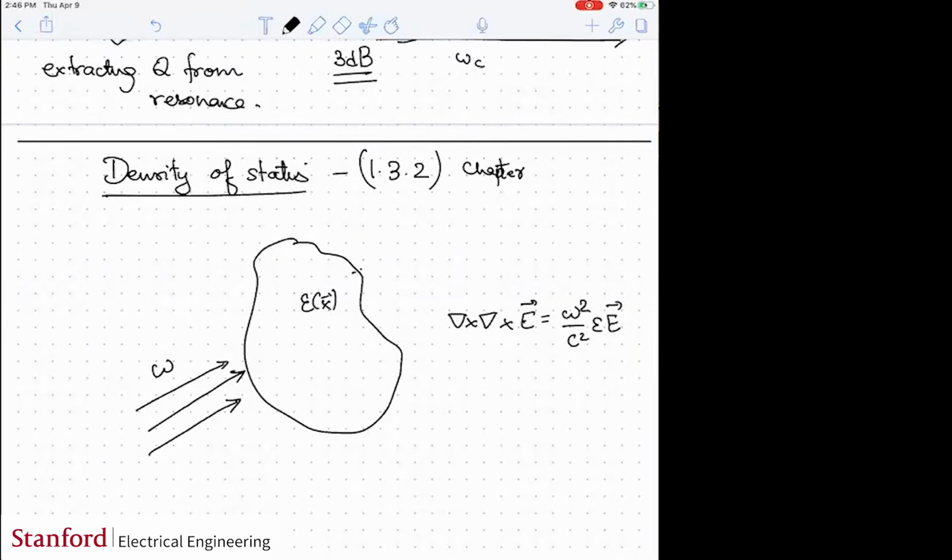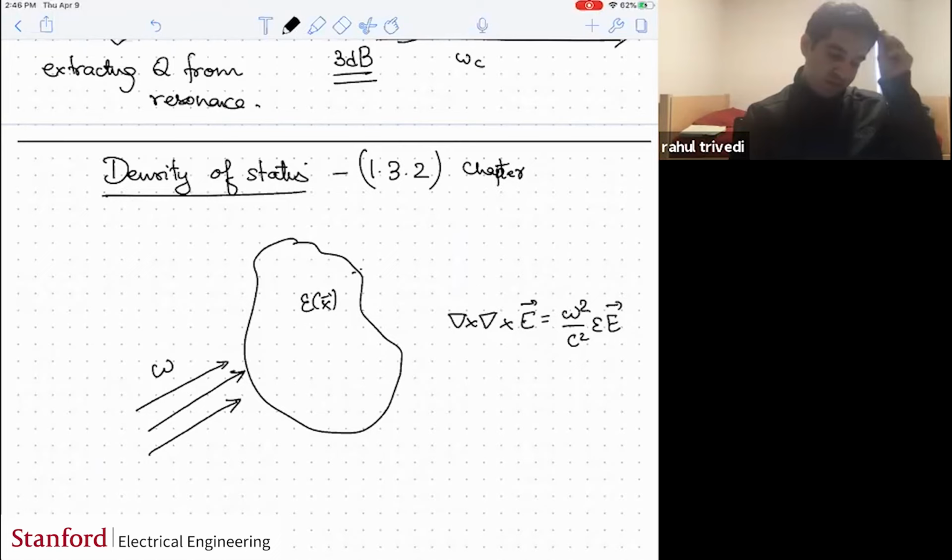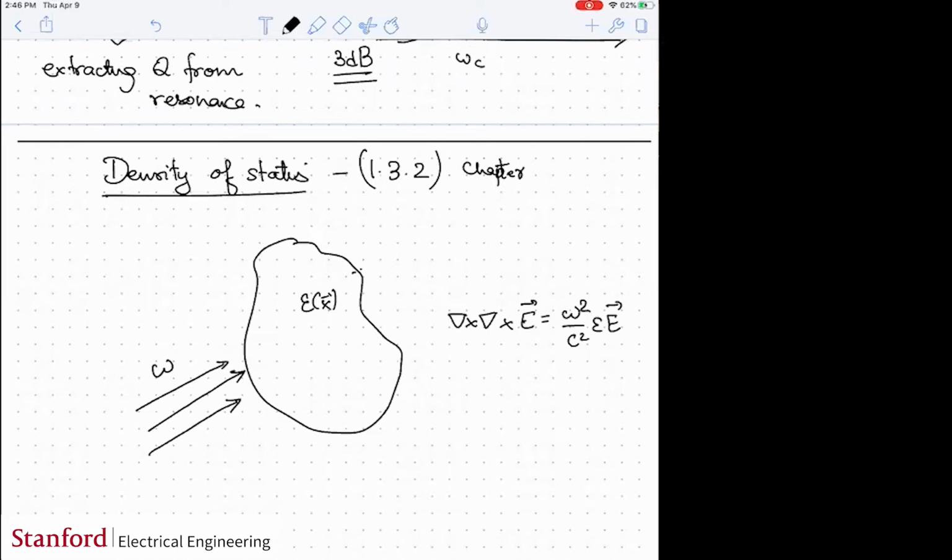Does it have to be a radiation boundary condition, or would this also arise from the absorption condition? That's an excellent question. If you have PEC boundaries, but with material absorption, then you can still describe the electric field with a discrete set of modes, because you could ignore the absorption and solve the lossless problem with PEC boundary conditions, and then you will still get an orthonormal set of modes that you can use to describe the dynamics of your cavity. The harmonic oscillator would just become a damped harmonic oscillator. That's what would happen.